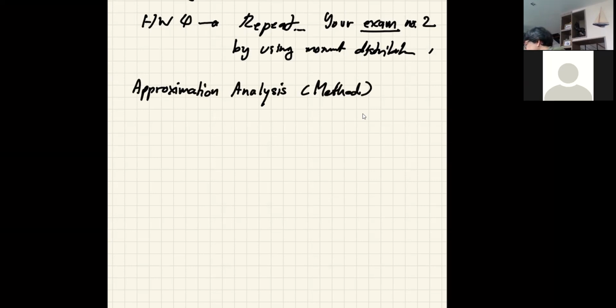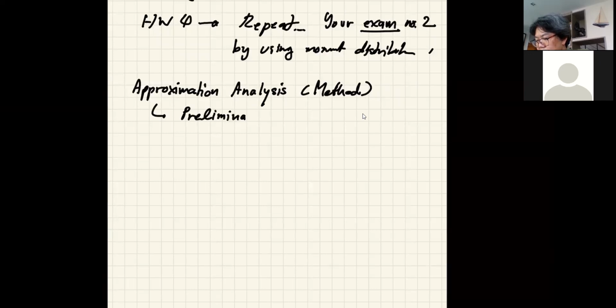Okay, actually, this is a very useful idea, and it's not that difficult to do. The approximation analysis requires quite a good few assumptions, and this is predominantly for preliminary design. Now, it may not give you accurate results, just like the slope, deflection, or moment distribution, but it is very good when you want to know the size of your structure from the beginning, and see if the configuration you choose for your frame will work or not, and stuff like that.